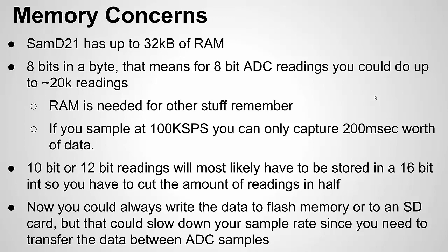Now, as I mentioned, we could write the data somewhere else. The SAMD21 has its own flash memory. It has direct memory access. We could use that to put the readings there, gaining us some more memory to store the readings. But remember, flash has a limited write cycle, so you can only write to flash so many times. And the flash on the SAMD21 is only about 200 kilobytes more of data or area. And of course, your program has to be stored in flash as well. So you're getting some more memory space if you use flash, but you're not getting a ton more.